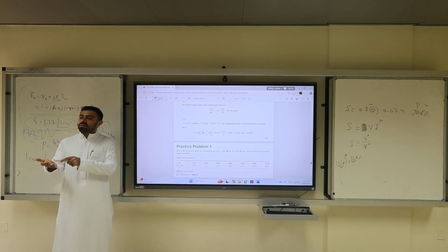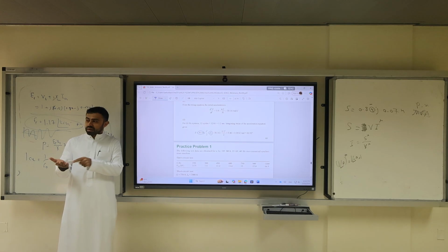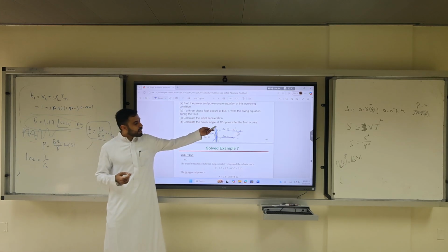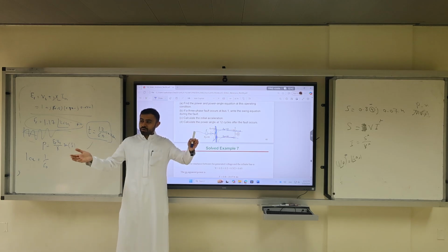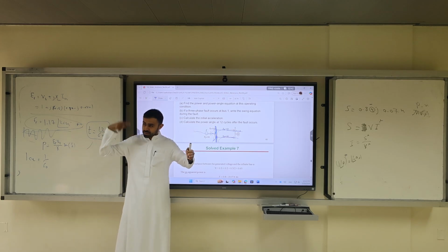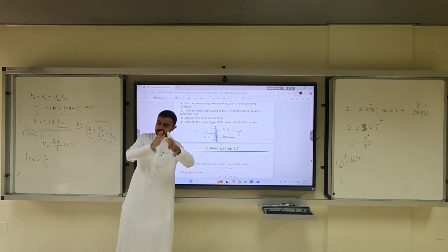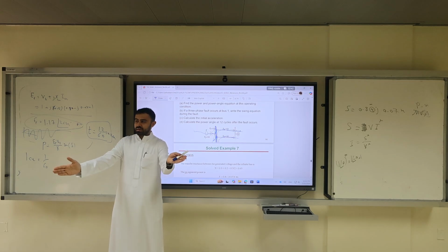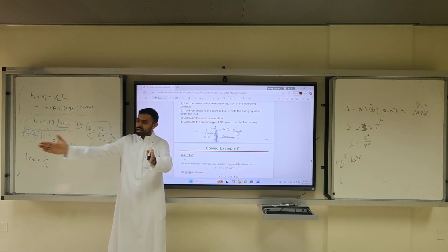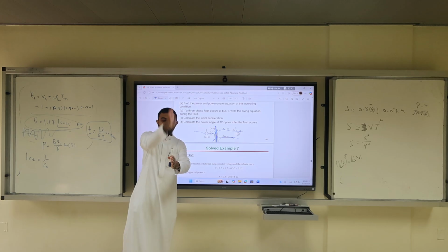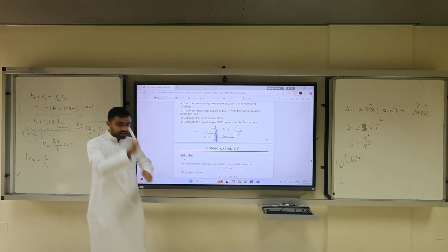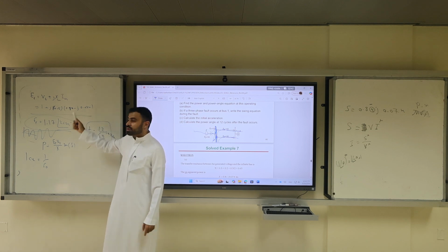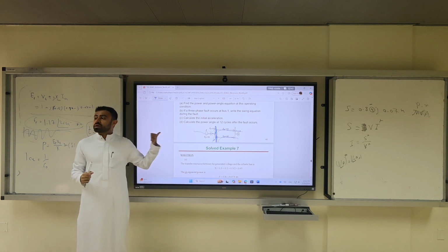So this is if the fault clears at 0.2 seconds. The question is asking to calculate the power angle at 12 cycles after the fault, assuming the fault keeps persisting. It doesn't mean it clears after 12, not clears at 6. If clearing happened at 6, we would return to steady state. And this assumes the fault stays all the way past the 12. What is the angle of your EF at 12 cycles, after 0.2 seconds? You can calculate it using the swing equation.